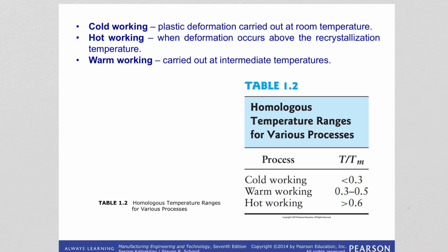So people need to come up with ideal optimum manufacturing parameters that will give them the most economical manufacturing conditions, basically. So sometimes they do cold working, and the cold working will give you an increased strength for the material, and there are some cases where we need to do hot working, and again this is above the recrystallization temperature.